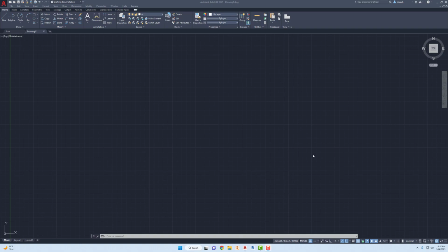okay, what is your drawing unit? Is the object that you're going to be drawing in inches? Is it in feet? Millimeters, centimeters? Is it miles? Is it in mini moons? I don't know, but that's pretty much the very first thing you should set when you open up your drawing. The way that I usually go about it is I'm going to type in the word units.